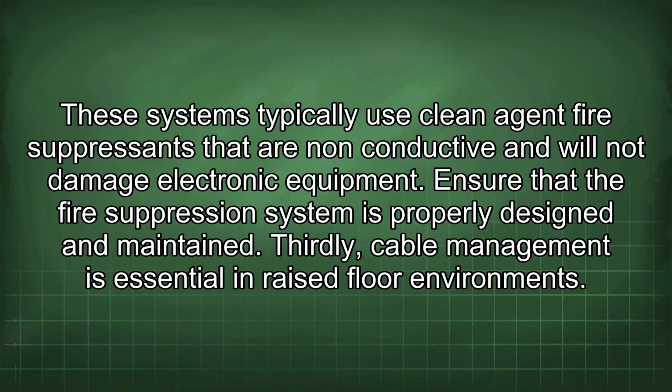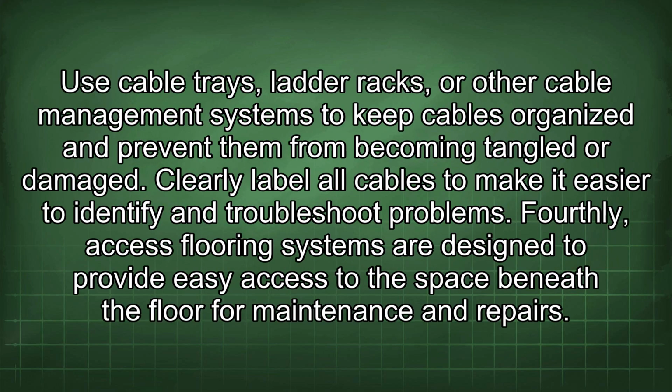Thirdly, cable management is essential in raised floor environments. Use cable trays, ladder racks, or other cable management systems to keep cables organized and prevent them from becoming tangled or damaged. Clearly label all cables to make it easier to identify and troubleshoot problems.